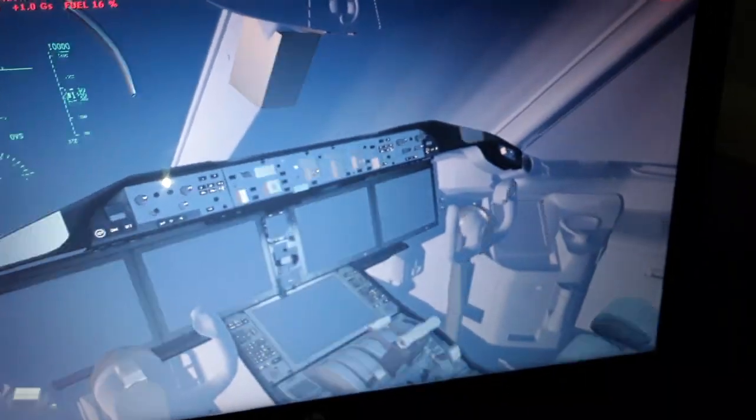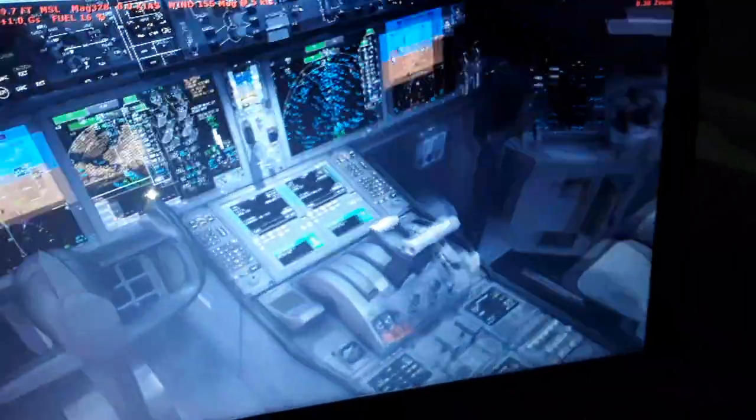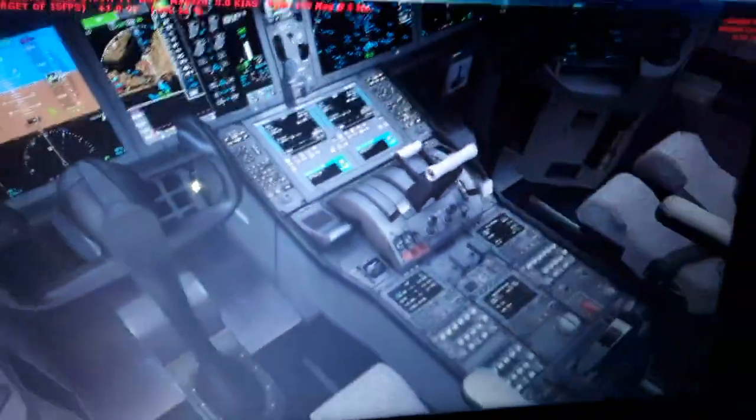So we have to disengage like this. For all Boeing 737, we're gonna lose the auto trim function. So this is for all Boeing aircraft. Actually, if you have a failure of some hydraulic system, that will affect also the motors that control the auto trim function.